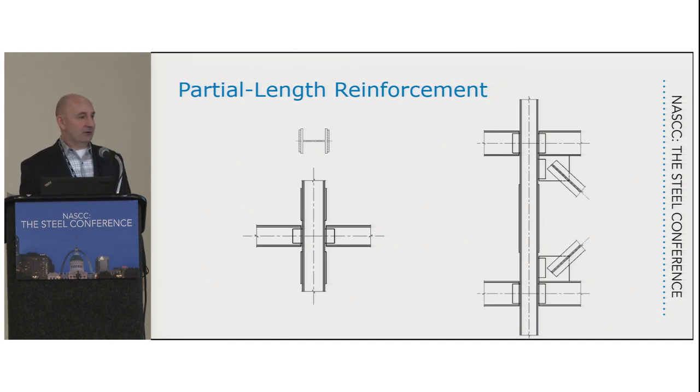And then there are situations where I've gone in and said, well, let's pull that back 3 or 4 feet just for economics, get less weld, less plate, and the column strength doesn't require it, then that can save money, and it can save column distortion, weld shrinkage distortion too. Now, typically, if I pull it within 2 or 3 inches, usually I'll give them about 3 inches there just to give them plenty of room to move it around. And if I end up with something that looks like that, typically I just neglect that setback dimension.